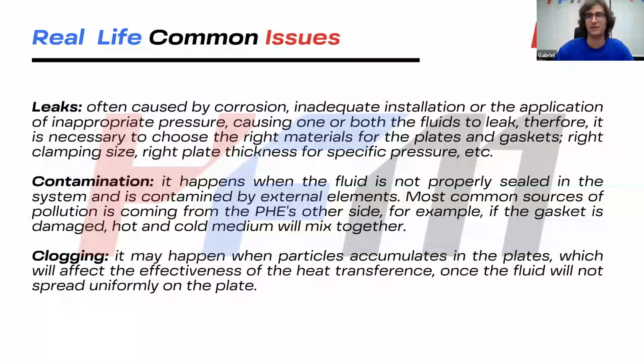Contamination also happens if you have a leakage, for example. It can also affect the integrity of the product. And for sure, the products should not mix together at all. That's the reason why we have the gaskets to seal, or the brazed plate, in order to avoid it happening. They're only going to exchange energy, heat, not mass at all.